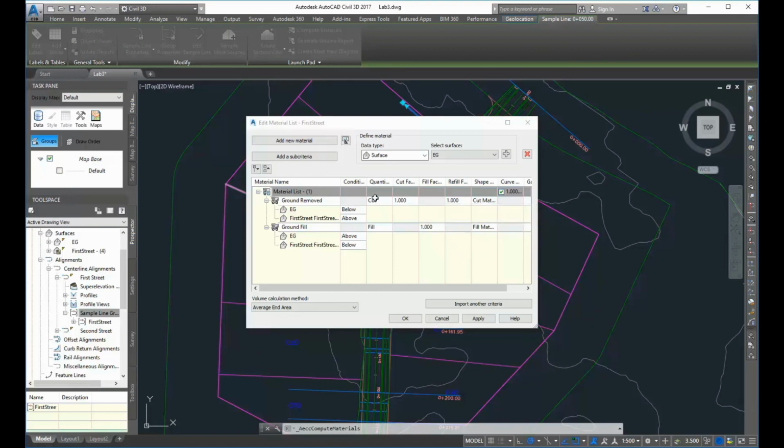When we cut out a cubic yard of material, so think of a yard, 3 feet by 3 feet by 3 feet, and we put it in a stockpile, and then somewhere on the project at a different station we know we need to use that material. Well, when we cut it out of the ground, it's compacted in what we call its in situ state. Depending on the geology of the site, it might be compacted to various layers.